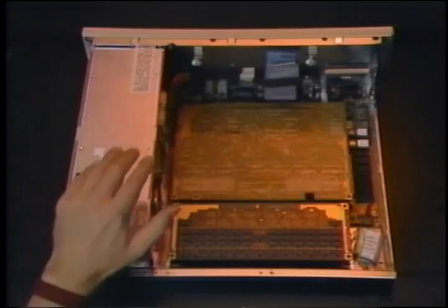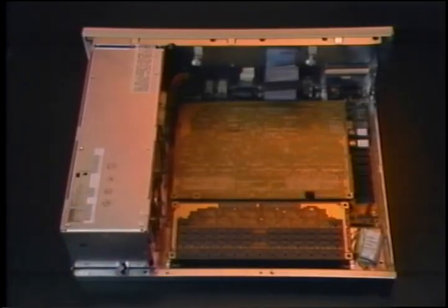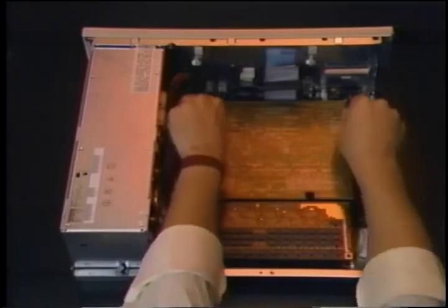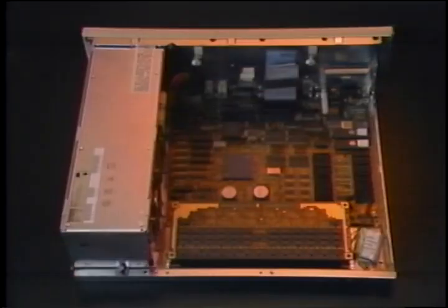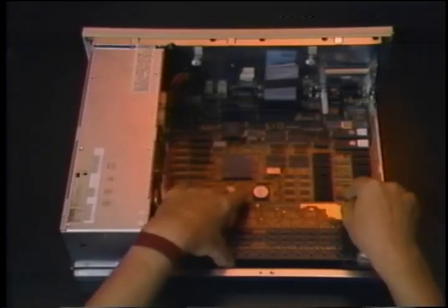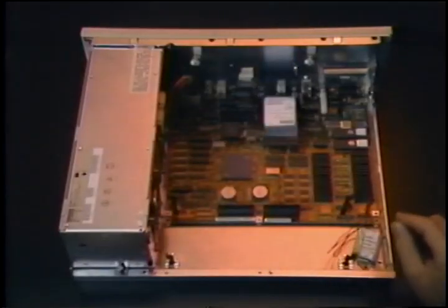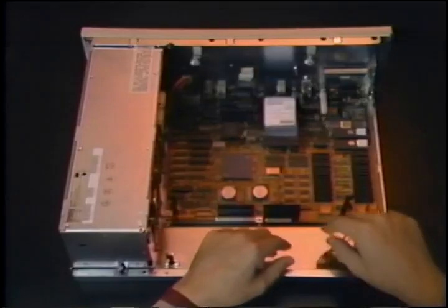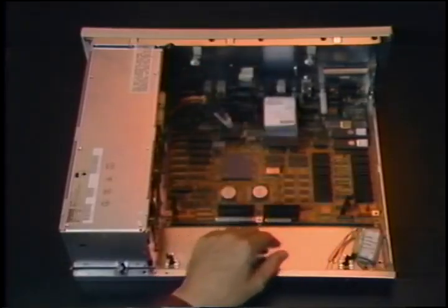At this point, the power supply can be removed. The color graphics module rests on 4 standoffs and connects with 2 50-pin connectors. Base system ROM upgrades can now be made. Memory options connect in the same way as the color graphics module. Disconnect the battery and system power. This action clears the NVR.